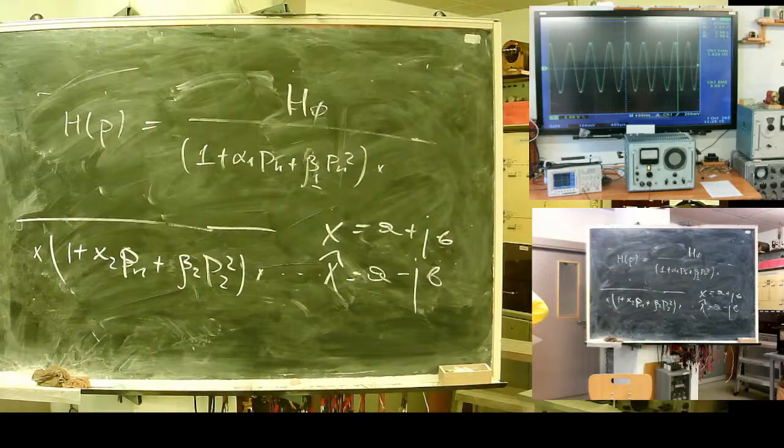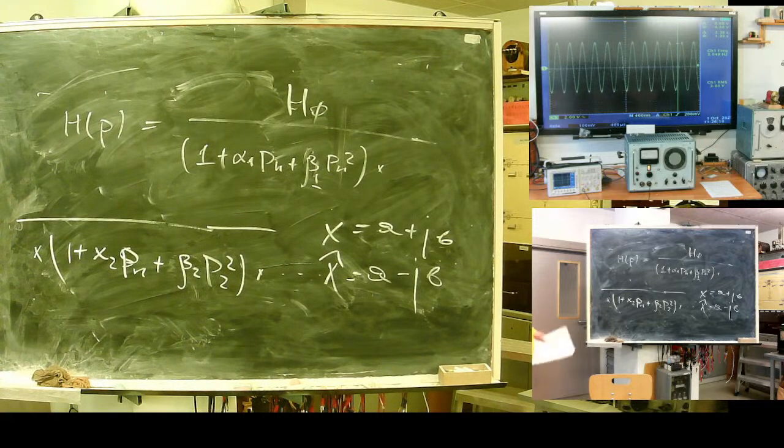So what's good in the switchable model? It's cheap. What's bad in the switchable model? Where's the problem with a switchable filter serving all channels one by one? You need to wait for transients to end. You switch to a channel and you have to wait until the transient ends. Only then can you measure. Then you switch to the next channel and again you have to wait. This downgrades your performance. If your system allows this setting time, okay, but if you need higher levels of performance, this will not work.